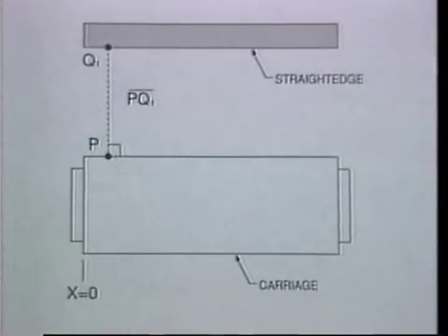Many measurement procedures involve the comparison of the specimen to some reference standard. An object's mass is often measured by balancing the object with an artifact of known mass, or the length of a workpiece is determined by comparison to a scaled rule. In such a manner, the straightness of a carriage or slide can be measured by comparing the slide's travel to